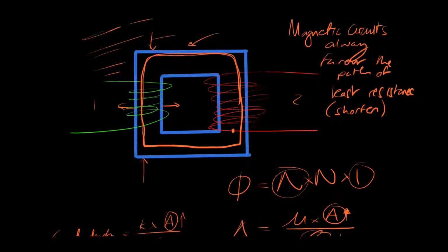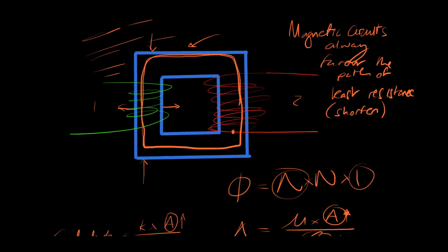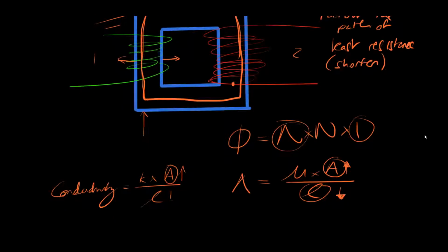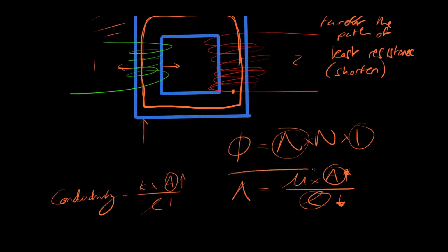However, in an exam situation where they ask you to try and improve a circuit, you have to look for factors like the permeance that's involved. Are there any air gaps in your magnetic circuit? Could you add a core perhaps? Could you increase the number of turns on one of the coils if you want to generate a larger EMF in the secondary coil? Could you perhaps decrease the resistance in the coils by making some adjustments?